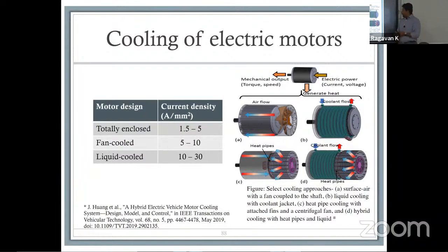The benefit of a cooling jacket really is that it is independent of the motor design. You design the motor, you put a jacket around it. We don't care how cold it is; we just find the right jacket for the occasion. So that's what this is. It basically gives you an afterthought on the thermal design. It's great. It's effective if you have the space.